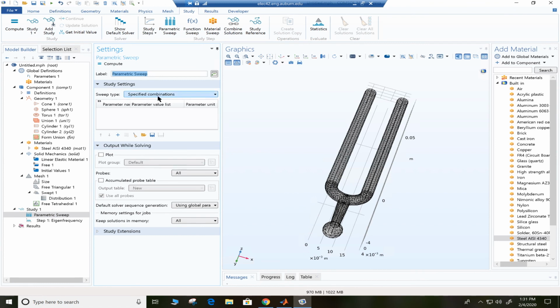And so what we want to do here, see this plus button right here? You want to add a parameter, how you want to sweep it. So you click on that, and it drops down everything that we had created, all the parameters that we created. If we don't list them, they'll default to their regular values. If we click on it, like this time we'll click on L, it's going to redefine our L for us. It's going to ignore the L that we had, and it's going to have this new L that we are going to define here with a range, with a sweep over.